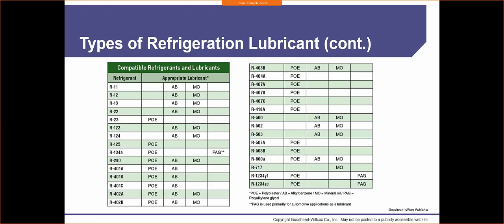If we looked at 407C, hey, look at that, POE. They say it's a drop-in replacement for R22. Nope, it's not. I have to put my synthetic oil in there first before my system is going to operate. It also says that in the fine print when you do try to put in 407C. So I just say, to heck with it. You know what? I'm just going to put you in a brand new system.